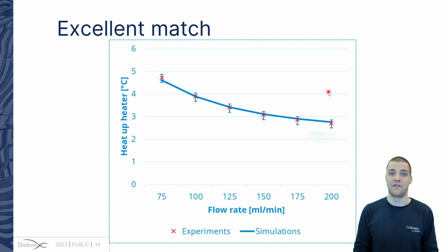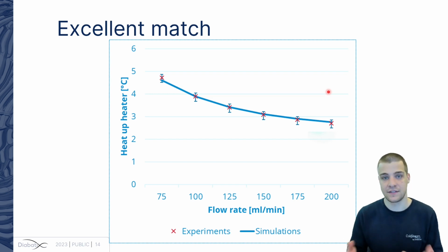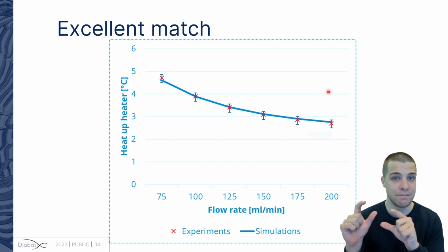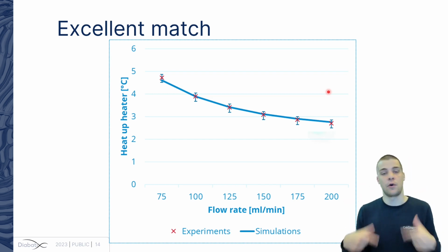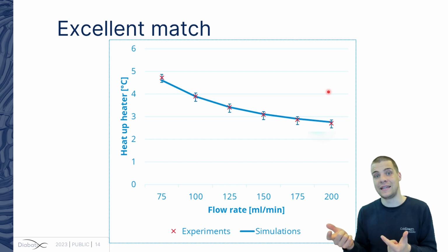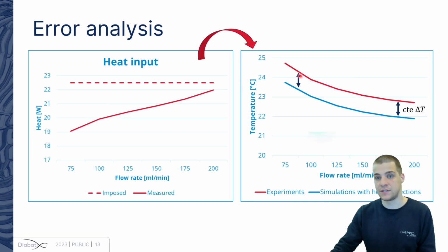And if we calculate the thermal resistivity, we have noticed that 1.8 microns of air, so a small air gap of 1.8 microns, can already accommodate for 1 degree of heat up, which is exactly what we see here. The average temperature delta is 0.8 degrees.